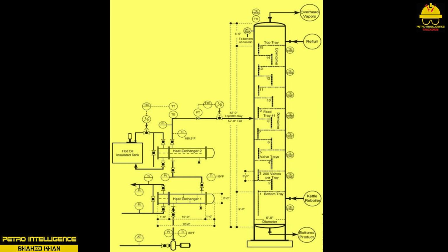Heat balance operates under the same principle as material balance. What goes in must come out and must be maintained in order to hold the heat balance. Initially, tower temperature gradients are established by engineering. The temperature gradient is the temperature profile that exists on the tower from bottom to top. Tower temperature is maintained so the expected separations occur. Temperature in a tower can be affected by pressure, flow rates, fluid levels, feed composition, reflux rate, and equipment problems.